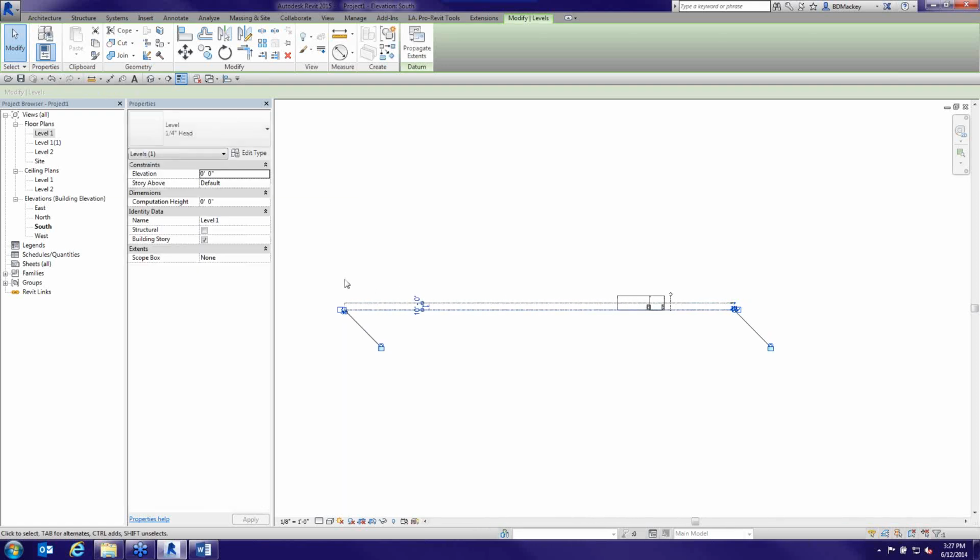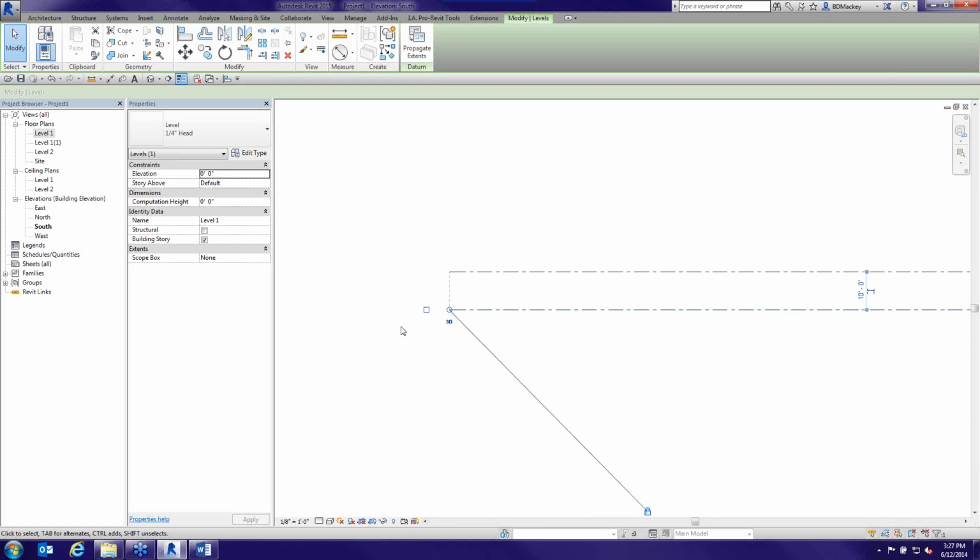This to me is a bigger tip than dragging the end. And the reason this is a bigger tip: on large files, as you zoom in and out, you've got a regeneration process. So I zoom in to find it, I zoom out to move it. I'm waiting 30 seconds, sitting there holding my mouse on the button as it's waiting to regenerate.